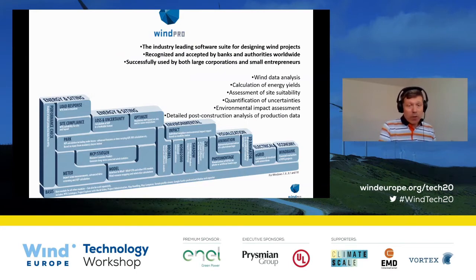and it covers a pretty large number of tasks, from the obvious wind data analysis and consequent assessment of annual energy production to the assessment of the uncertainties and losses for so-called bankable reports, the assessment of the suitability of a given technology to a certain environment based on the IEC standard, the estimation of the environmental impact in terms of noise, shadow flickering, and visual impact of the turbines.